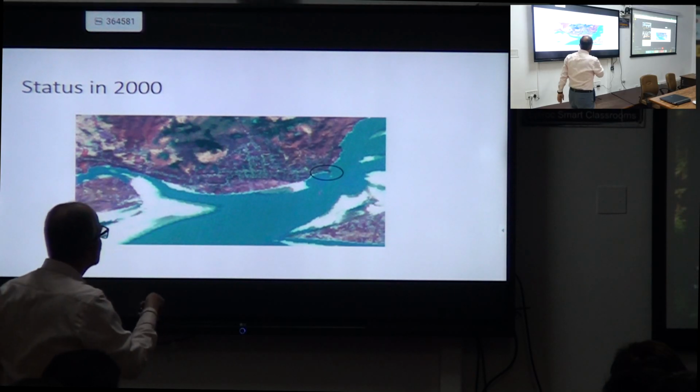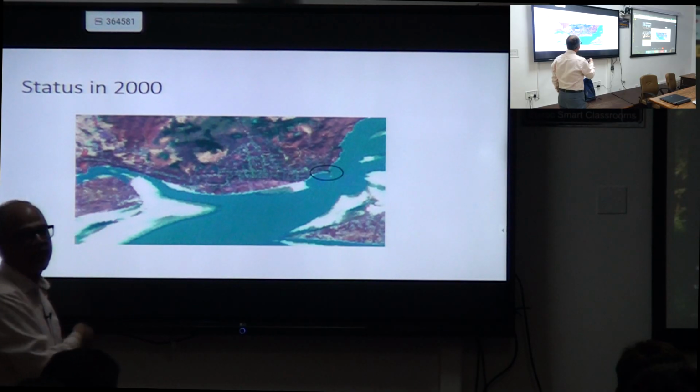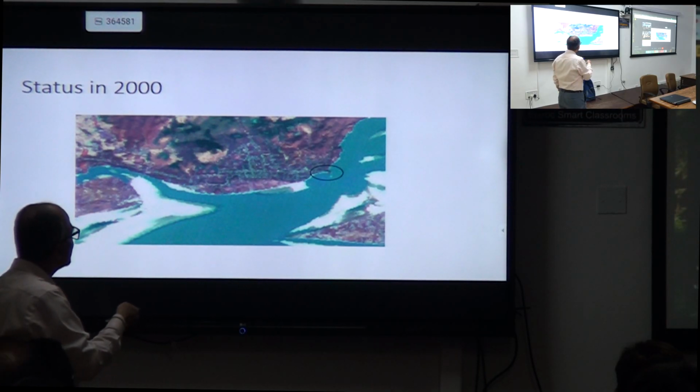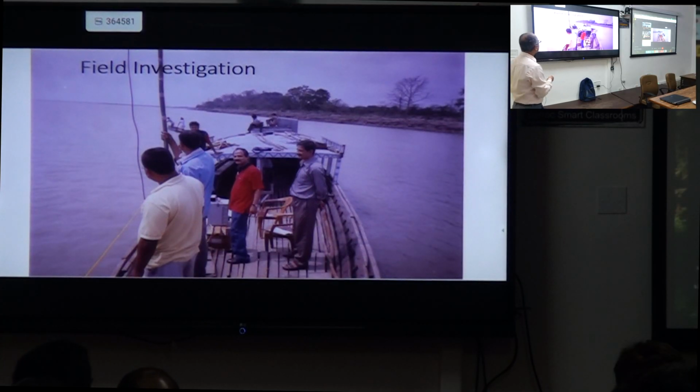So at this hill outcrop, a temple was constructed, and because of that, some portion of the hillock, rock was taken from there. Blasting was done, and it took a shape. Some boulders fell in this position and it has become an attracting spot. Because the shape has changed, flow was coming from this side and going like this and circulating like this, and it caused a huge erosion in this part, taking all these 34 houses. Now you can see how long it is.